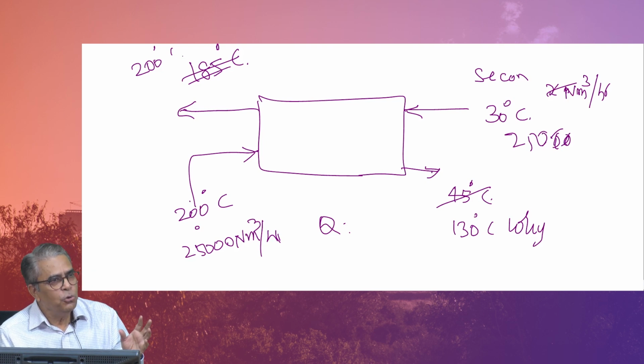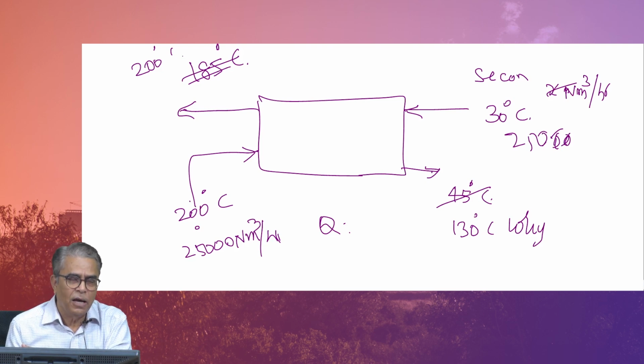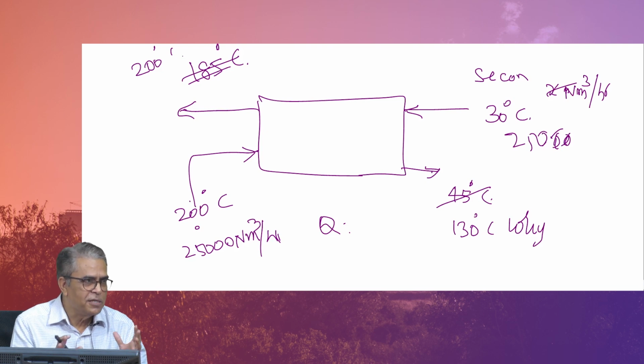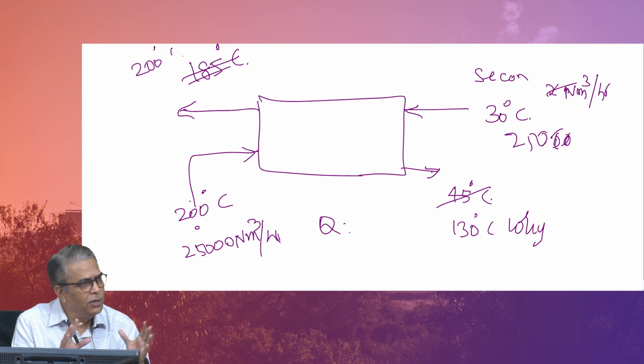There, usually, based on a large number of surveys of manufacturers, the approximate expected pressure drop of heat exchangers of various types is given. Usually it will be of the order of 75, 100, 125 millimeters of water column. That is about all the pressure drop that comes, because the logic being the pressure drop should be sufficient to get mass transfer, but at the same time low enough to limit energy loss. All this is known from historical times. So, people had worked it out and kept it there.